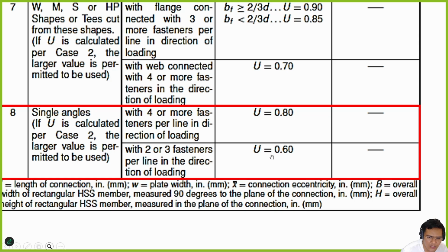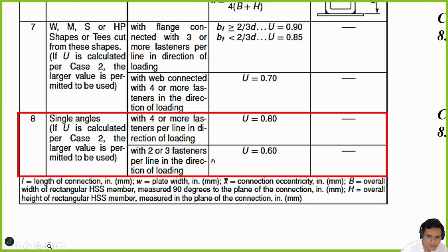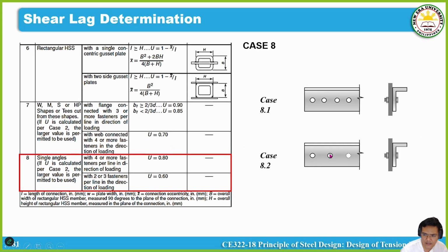So, ang reason doon kasi the number of bolts affects the amount of... basically mas marami kasing bolts, mas marami magtutulong-tulong, no, to carry the loads and to transfer, no, from the applied load. Kapag konti, mas critical 'yon. Kumbaga yung shear lag mo mas observable doon. Okay? So mas malaki yung nababawas sa area net mo. Okay? So yun yung explanation behind that. Okay?